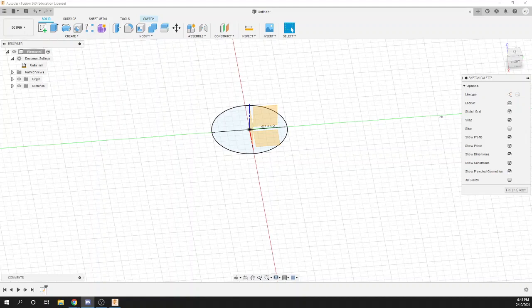Oh, I'm sorry, I'm not sure if I caught that. Yeah, so I cannot see them. Okay, so you're in Fusion right now. Awesome. What's probably happening is I bet this eyeball next to origin is unclicked. So go and look in this left-hand bar and see if you can toggle the eyeball to be on, so that you can see all of the coordinate axes and origin as well. Did that work? It worked. So that should be good to go.